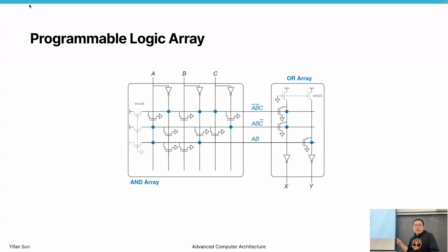So what an FPGA does beyond simple combinational logic is combine different lookup tables together with registers, so it can also support sequential logic. And today, FPGAs are much more complex than the early-days FPGAs. For example, FPGAs are equipped with multipliers. You don't want to use a lookup table to multiply data, right?